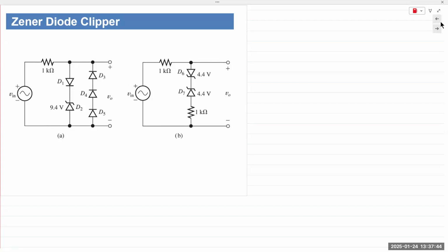But if you use a Zener diode in place of a battery, a Zener diode is used or operated in reverse bias. So it's 0 volts in a Zener diode until it breaks down. And once it breaks down, it holds the voltage constant at a particular level, VZ. No battery required. And so VZ is what we obtain at the output.